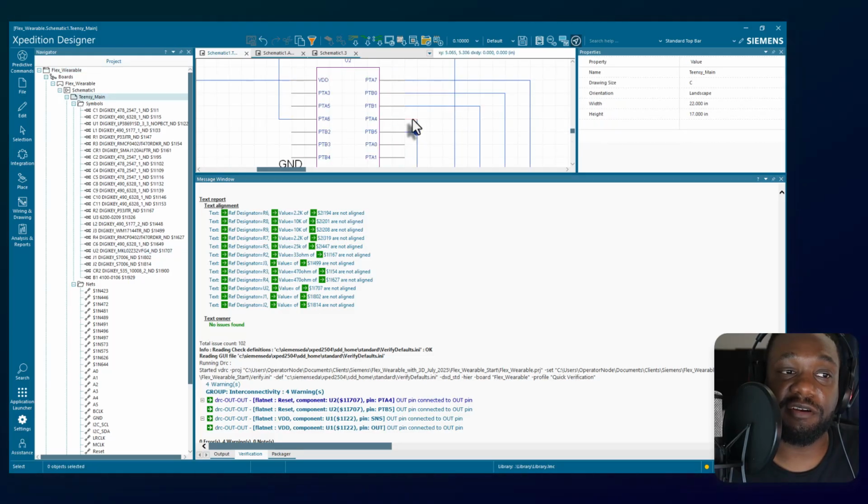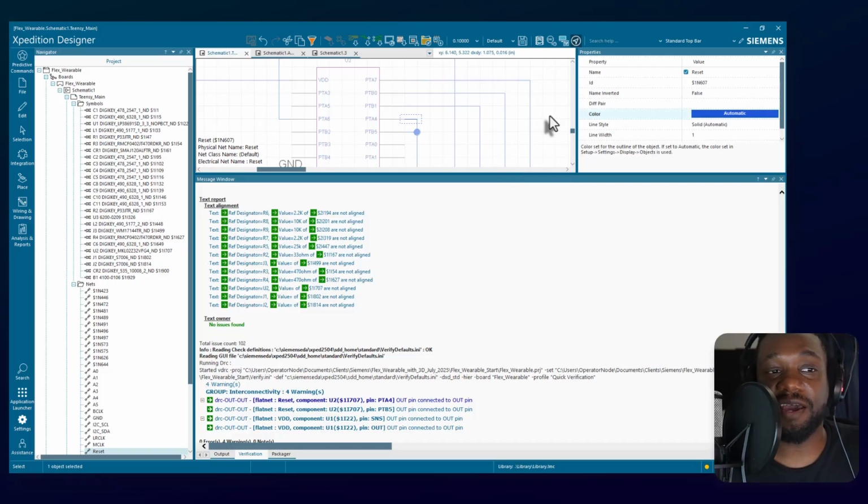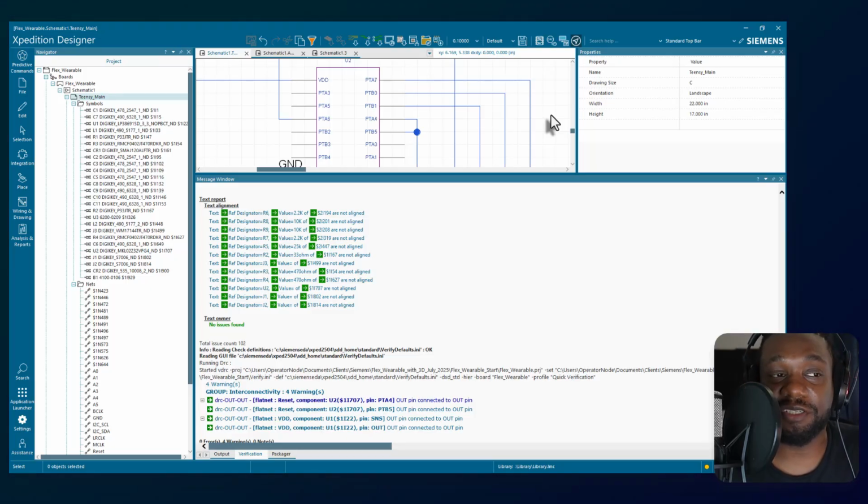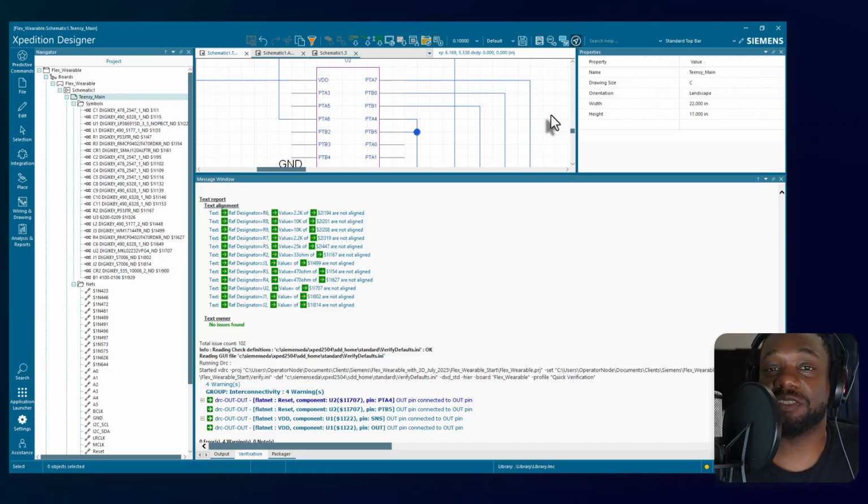And then you can verify that it's the correct type. In fact, somebody commented on one of my videos to find out how important the pin type is to specify or verify. It's very important, especially for debug issues. You don't want to have an output pin connected to another output pin by mistake just because you set it to unspecified and forgot to check something in the datasheet. You don't want that. With the right pins, it does inherent debugging for you, makes your life easier.